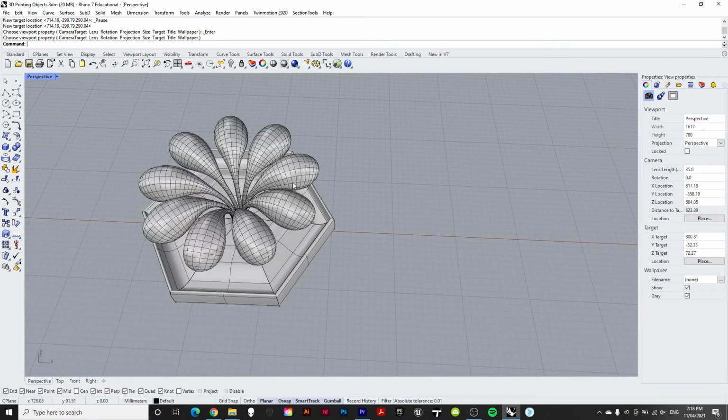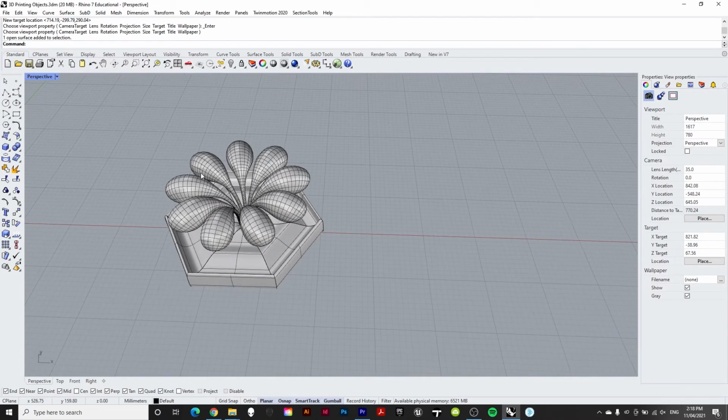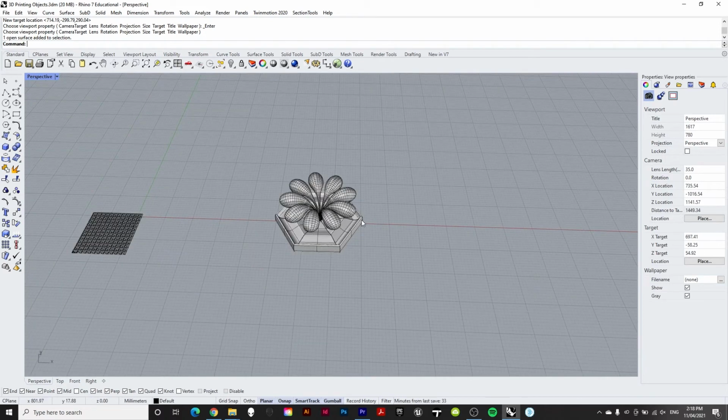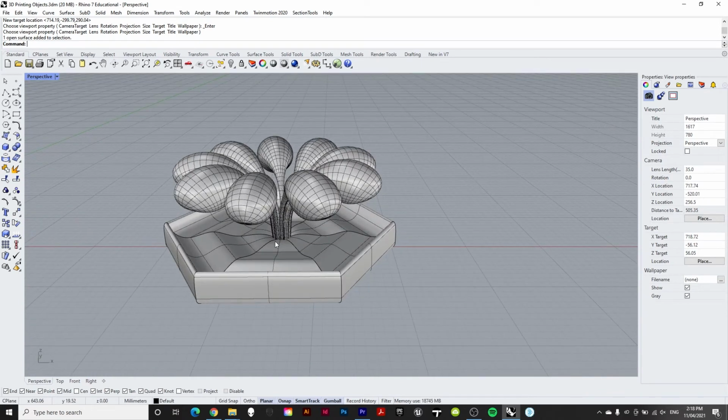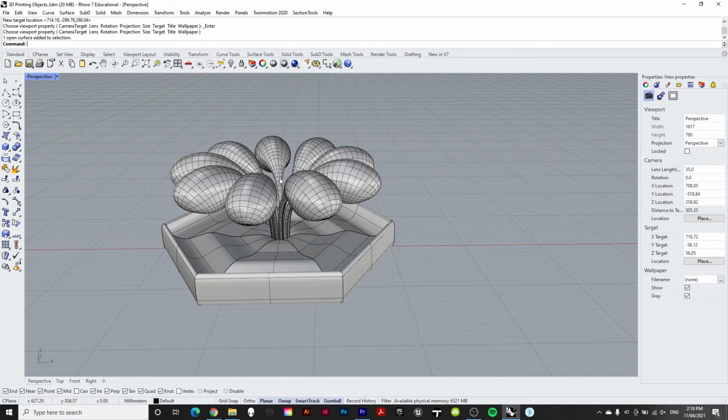So what we want to do if we have a geometry like this, which is made up of multiple parts, is think of it like we do in the laser cutter video, as an assembly method. So rather than constructing it out of one solid part, what we would do is break this down into its core units, into units that can be easily 3D printed, and then put them back together once they've all been completed.